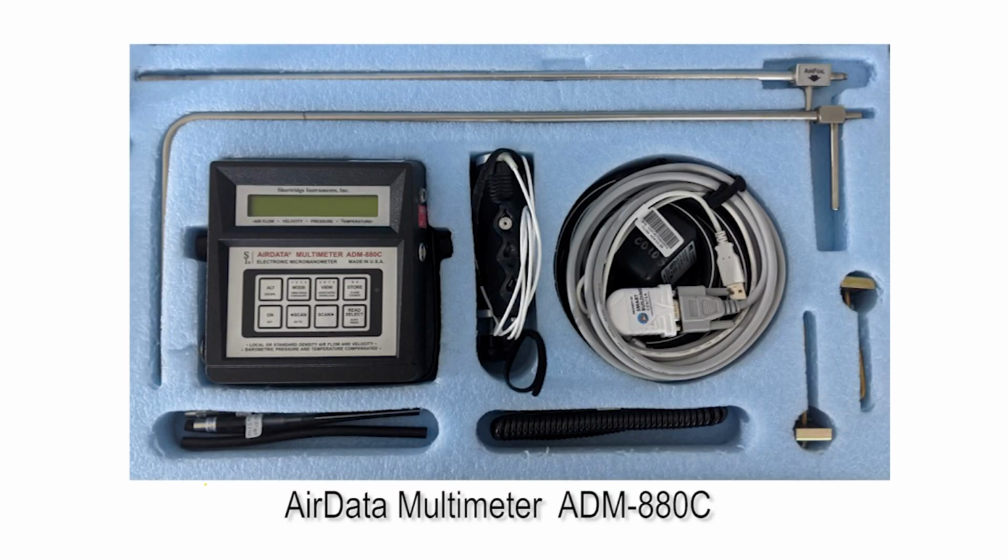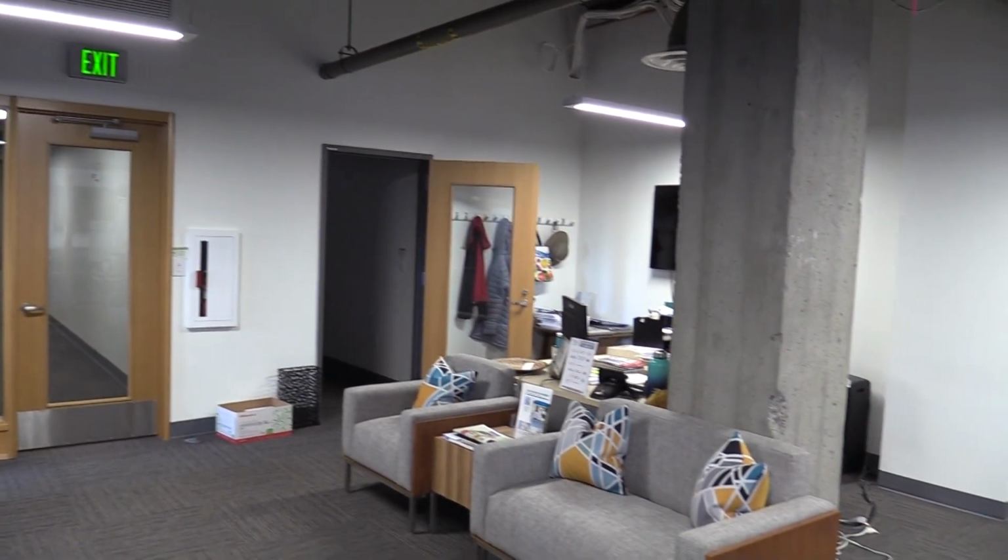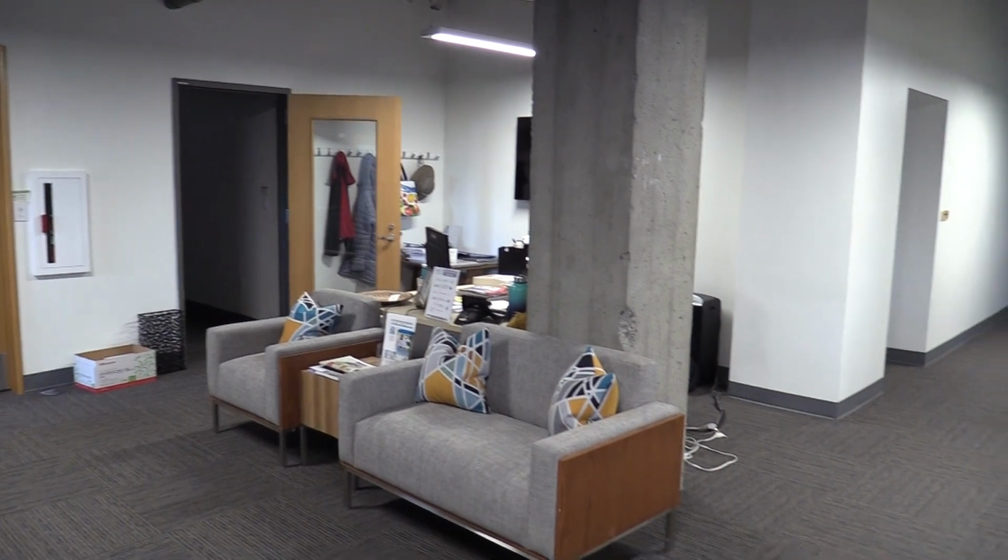Today, we will demonstrate the AirData Multimeter, ADM-880C. We're going to demonstrate how to use it in combination with a pitot tube to measure the airflow going through a duct into our space, the reception area.